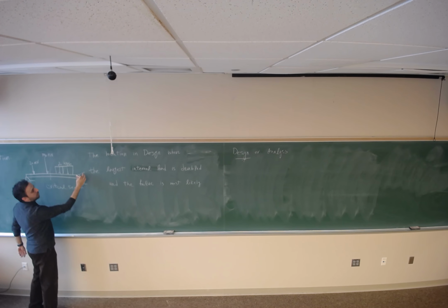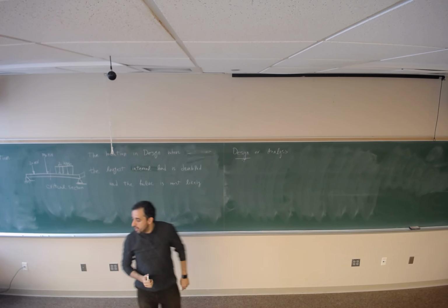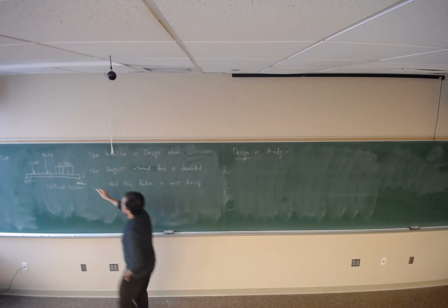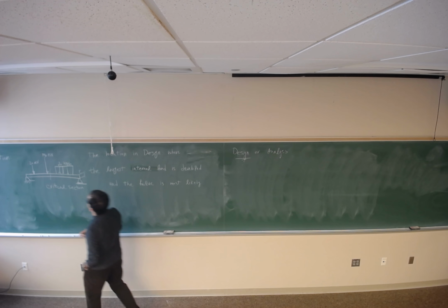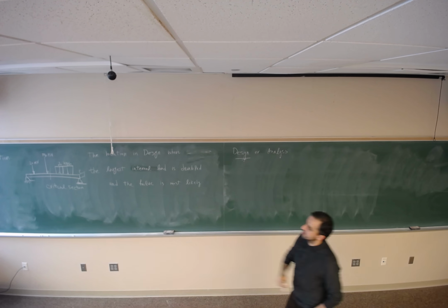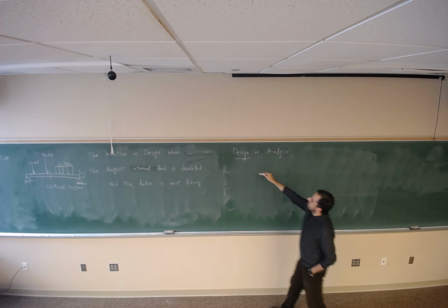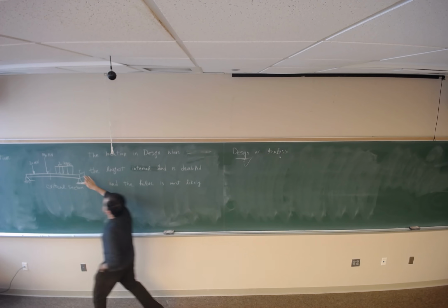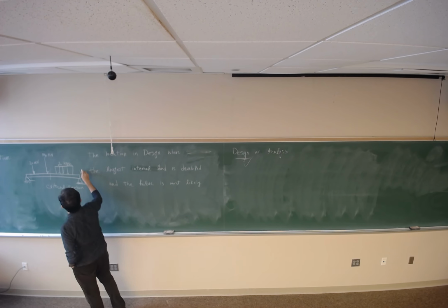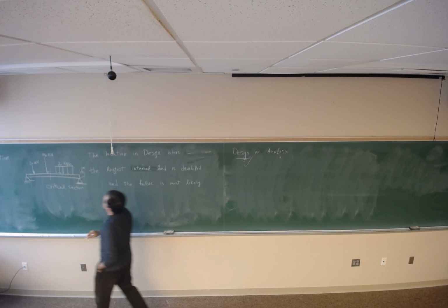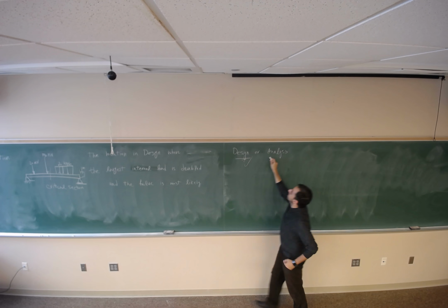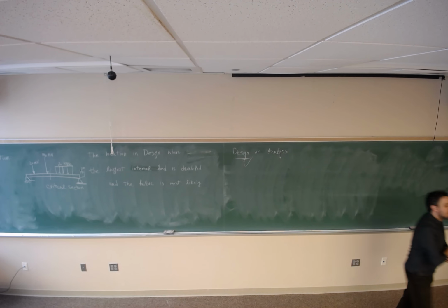Suppose you have a square cross section, you are sizing the thickness of this beam such that it's not going to fail. This is the design. And what is the analysis? If t is given, suppose 1.5 centimeter, and the length and other things are given, you are answering the question of whether we have failure or not.